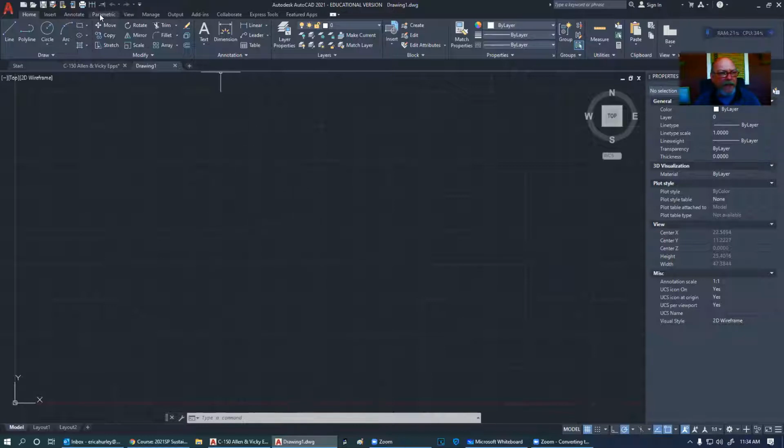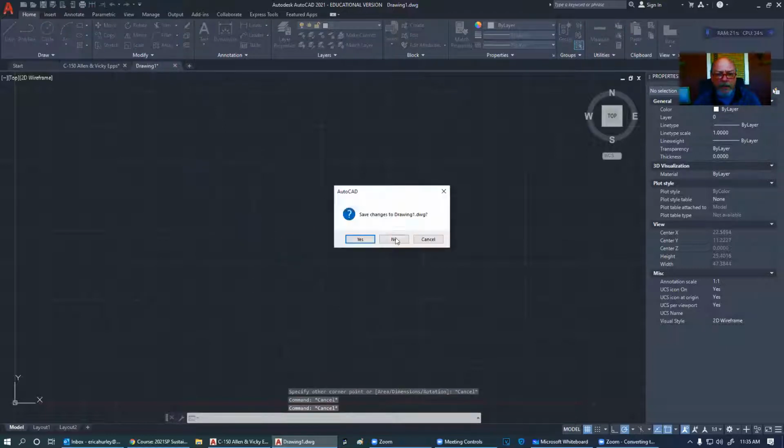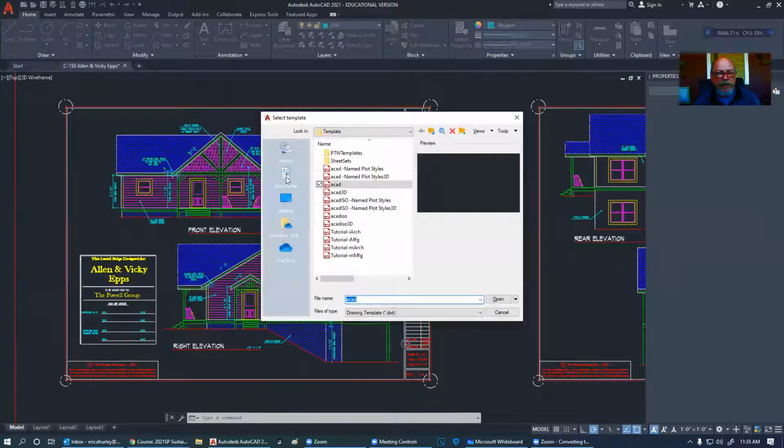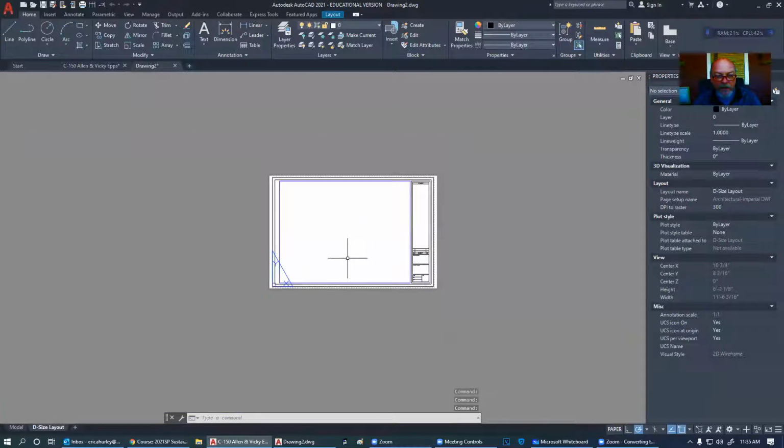When you first open up CAD and you go to make a box, for instance, you'll notice that your cursor is going to pop up stuff like 3.49. That is because CAD was originally invented to do mechanical drawings. So these are decimal inches. When you click on new and it opens up, you'll come down through here and you'll see something called traditional I-arch. What that means is imperial architecture.